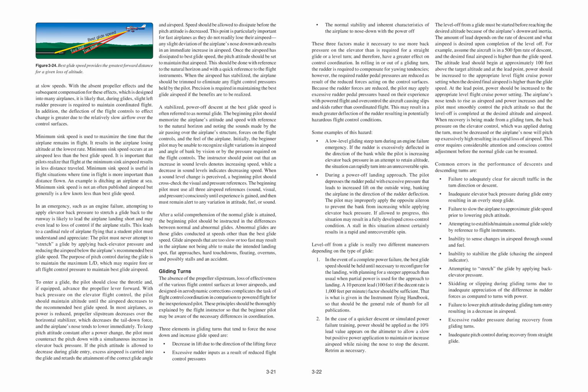Gliding turns: the absence of the propeller slipstream, loss of effectiveness of the various flight control surfaces at lower airspeeds, and design and aerodynamic corrections complicate the task of flight control coordination in comparison to powered flight for the inexperienced pilot. These principles should be thoroughly explained by the flight instructor so that the beginner pilot may be aware of the necessary differences in coordination.